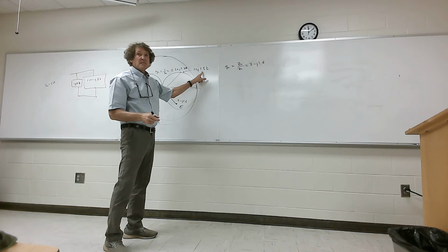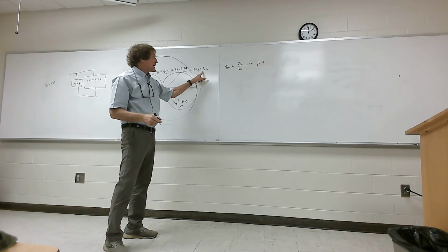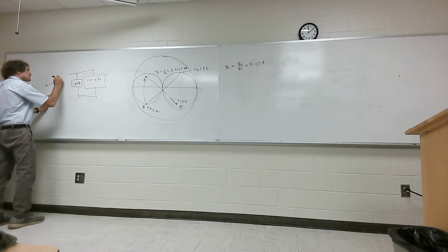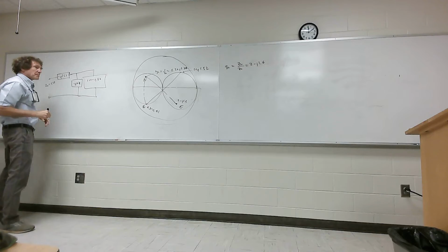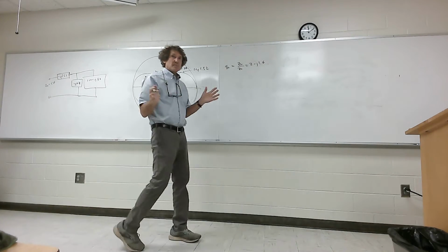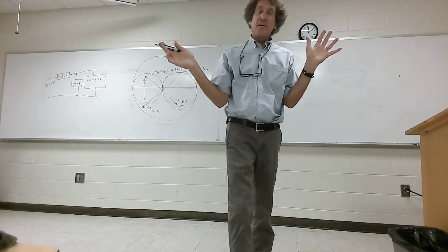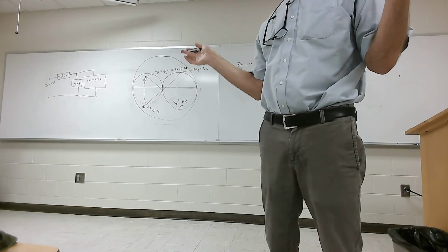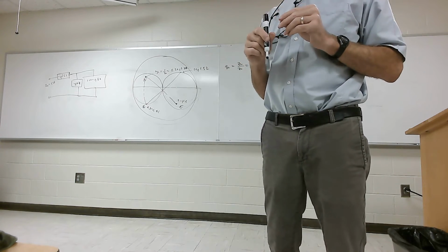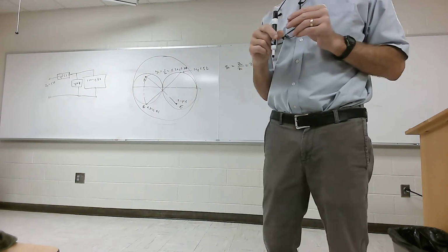Now we're in the impedance domain, correct? We've got to add a minus J 1.52, right here. And then we'll be matched, okay? Now, does everybody follow? I did the same method, but I went the wrong ways in a sense. I've got an inductor in parallel, and I got a capacitor in series.